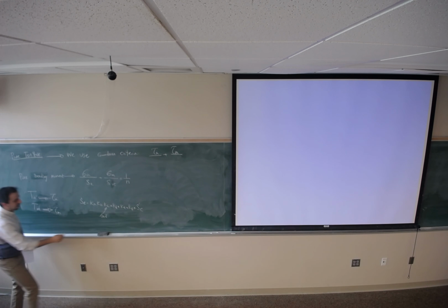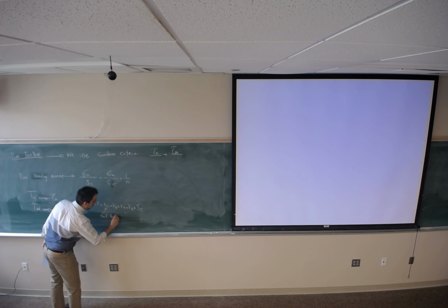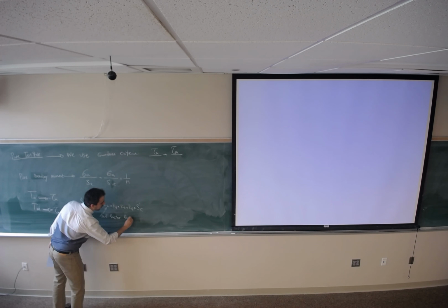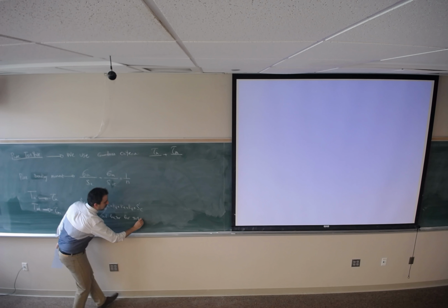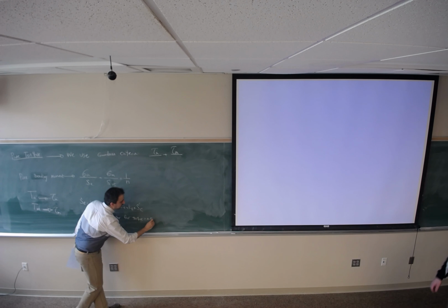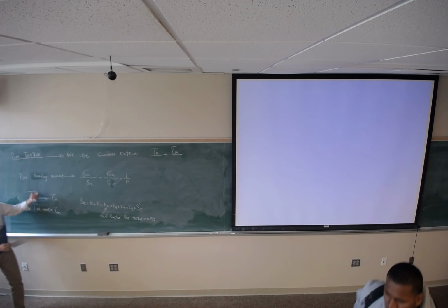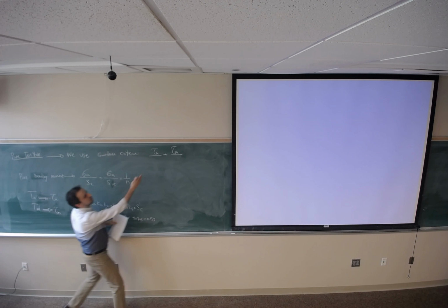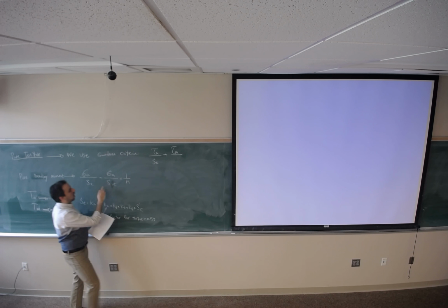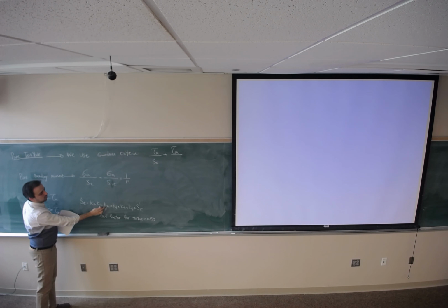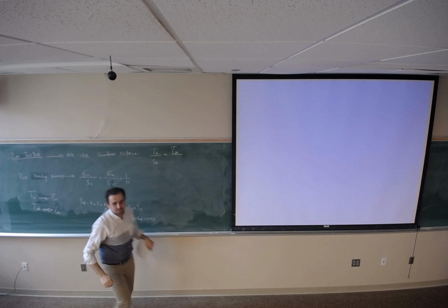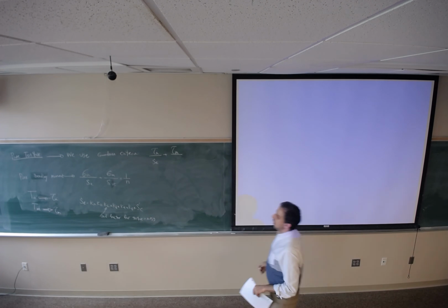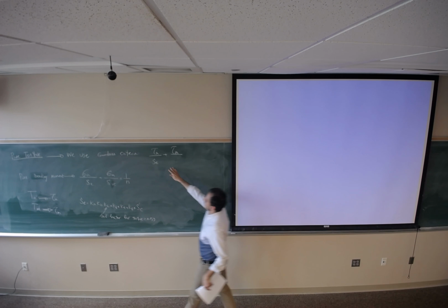Load factor for torque is going to be 0.59. So when I'm moving from bending moment to the pure torque, I don't need to do anything. I just use the corresponding factor, 0.59. I modify this by applying 0.59 to the SE. So whatever SE is going to show up here.